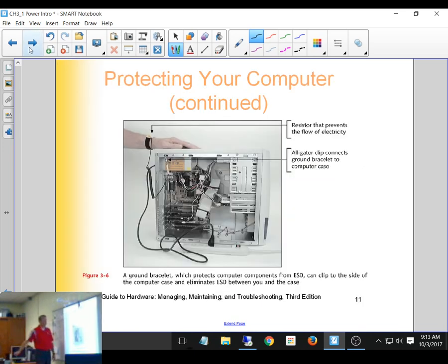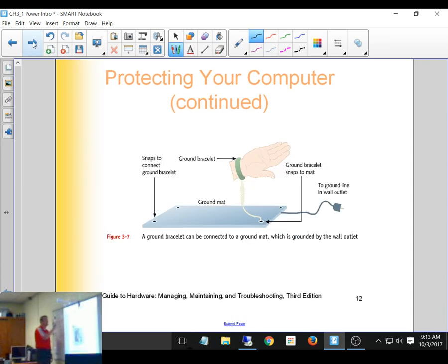Okay. So there's our grounding strap. You can see it's connected to the case, but then the case is plugged in. You're like, it's plugged in, but it's not really. This cable only has a grounding wire. So this case is grounded with a grounding wire. It's not really plugged in, although it looks like it in this picture. And then he's grounded to the case with that grounding strap. So that's what that is.